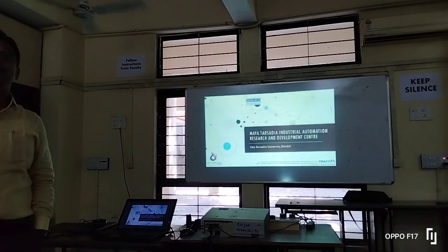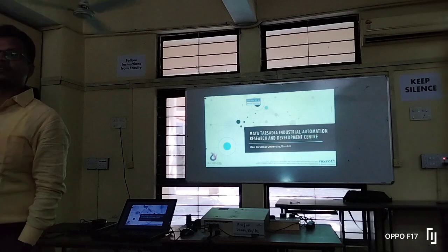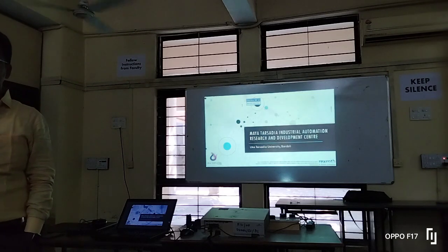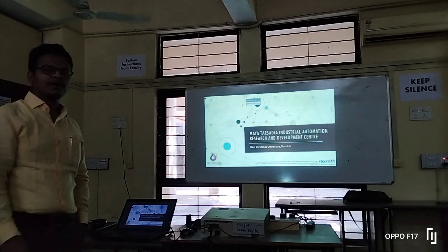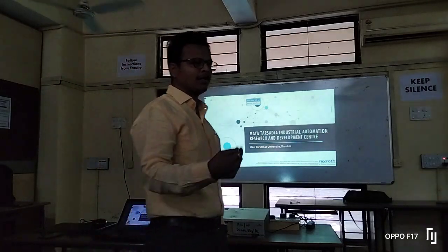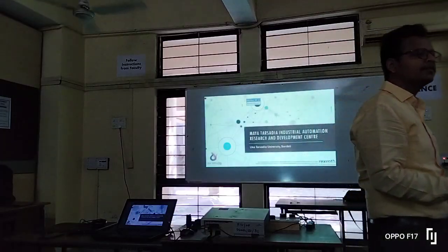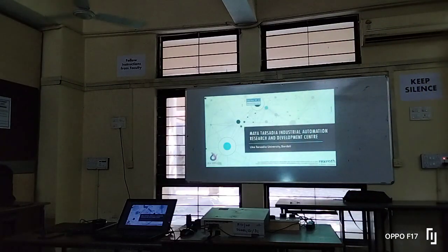If your 8085 processor having 16 bit of address line, how much capacity of memory you can connect? 2 raised to 16 multiplied by 8 bit, because data line is 8.